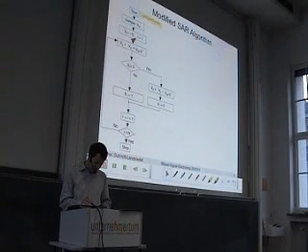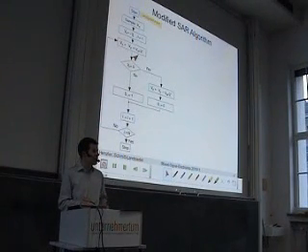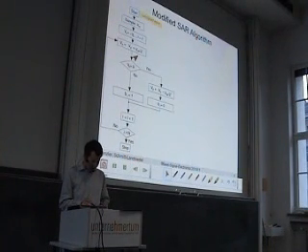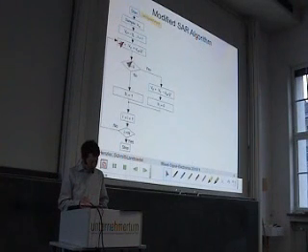Then we first increment the Vx. Okay, this is different to what we did so far. So far we checked first against the internally generated voltage. Now we first increment the internal signal. And then we do not check it against the internal voltage, but we always check it against 0.